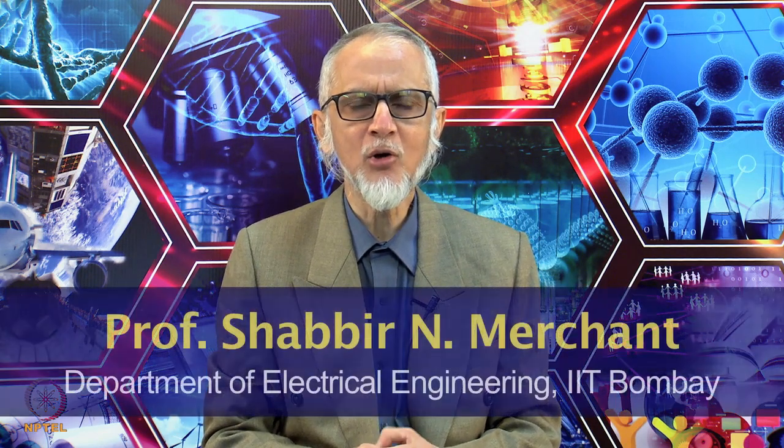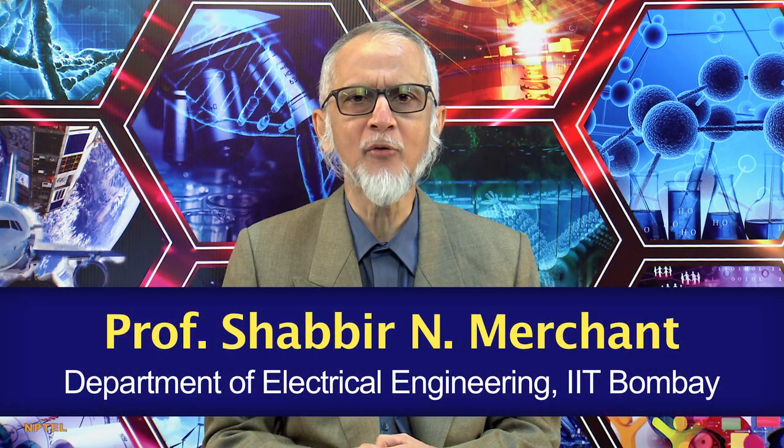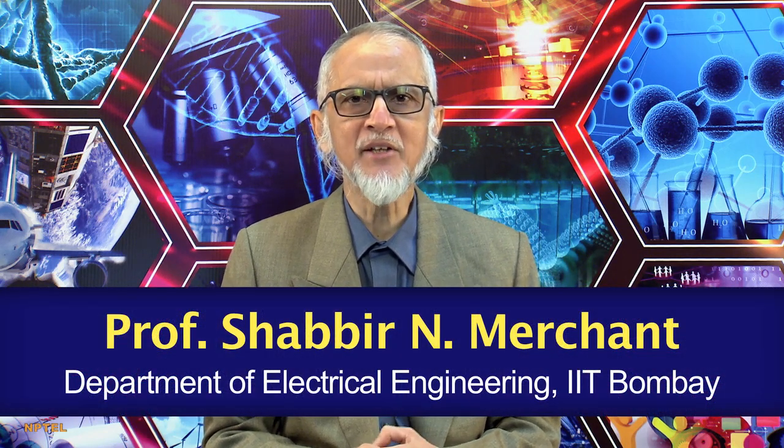In M-ary ASK and M-ary PSK, the messages, which are patterns of n binary digits where n is equal to log to the base 2 of M, where M is the number of messages, are encoded either into amplitudes or phases of a sinusoidal carrier.